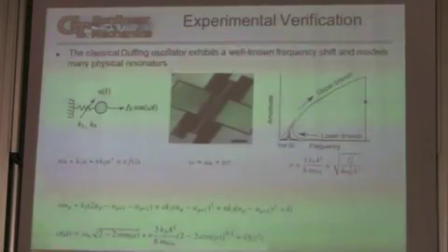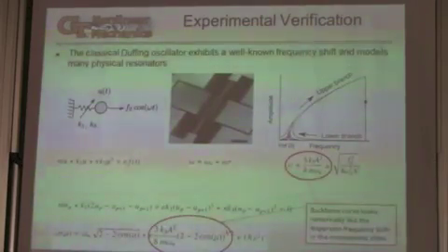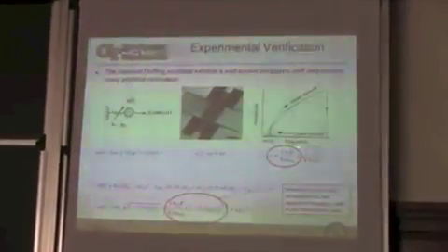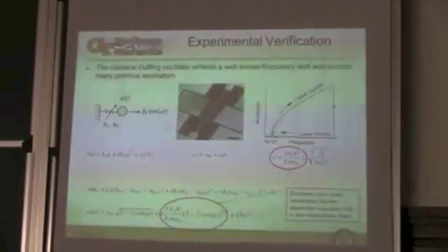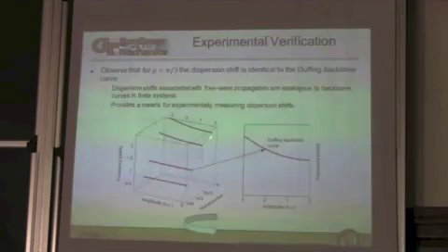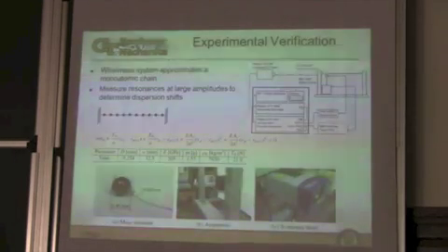We've now done one experiment. I think I'll close on this. We've done one experiment really relating the classic Duffing oscillator, which would be here. Here's its frequency response. This is the backbone curve. Two dispersion curves. Now, I've been showing you pictures that are just simply this front face. Here's your wave number. Here's frequency. But as you change amplitude, you get a whole family of dispersion curves. And we can measure these in a simple periodic string, and we've gone and done that, in fact.